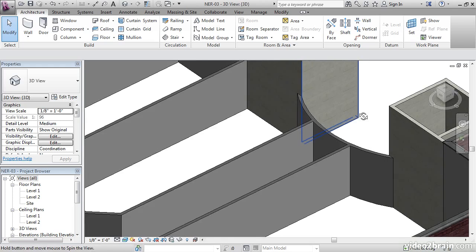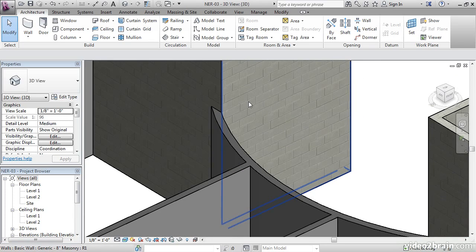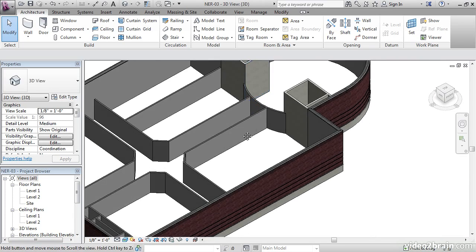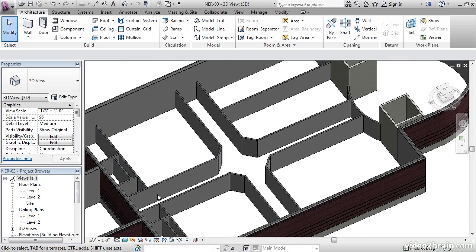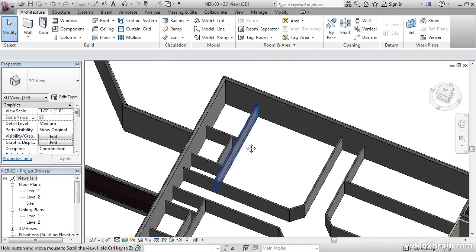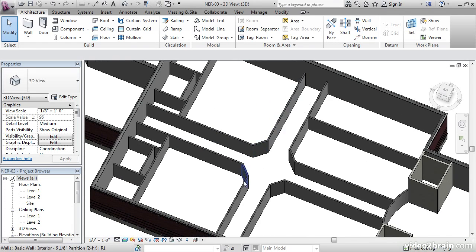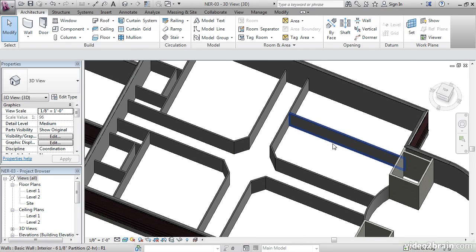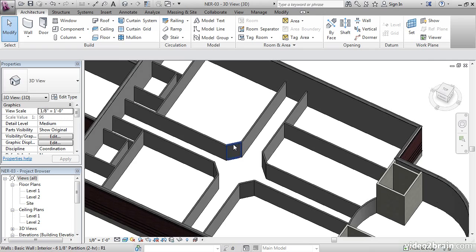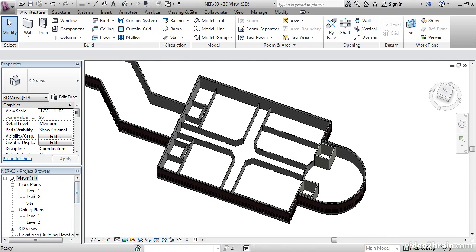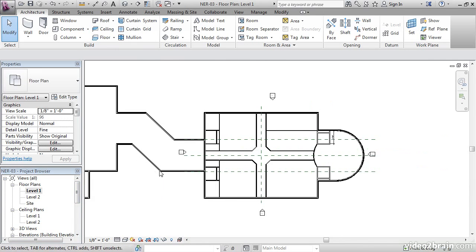The first thing we're going to do is start with a radial wall that's going to be appended to our masonry walls. The second thing we're going to do is throw in a corridor. The third thing is throw in two lavatories. We're going to add a corridor here, add a little partition here, and maybe if we have time, add these 45-degree angles. If we look at it in plan for floor plan level 1, we'll see the layout.